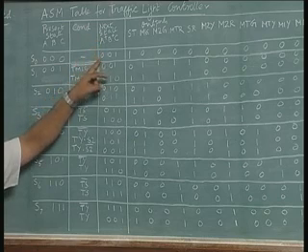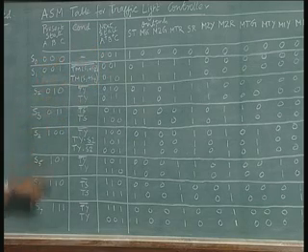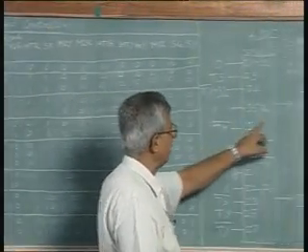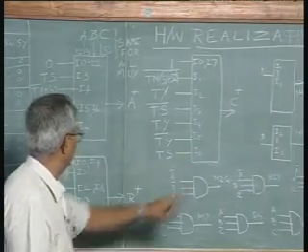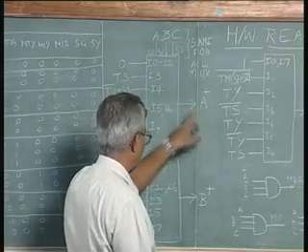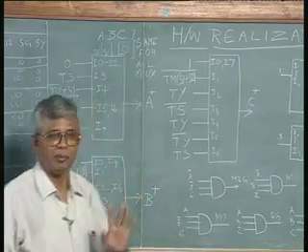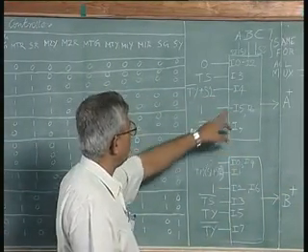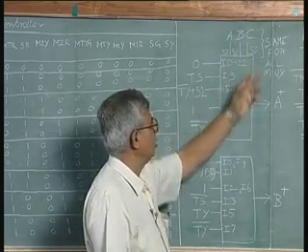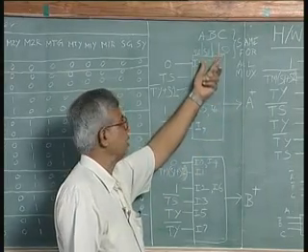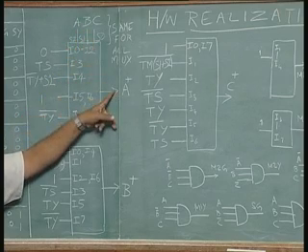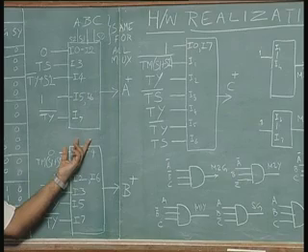So we have 8 to 1 multiplexers with 3 selector variables ABC. There are 3 multiplexers required here: one for A, one for B, one for C. We call the outputs A plus, B plus and C plus to indicate they are next state variables, and what state they are in is given by the inputs ABC. ABC inputs are given to selectors S2, S1, S0. Each 8 to 1 multiplexer has 3 selectors S2, S1, S0, to which we apply the present state ABC.